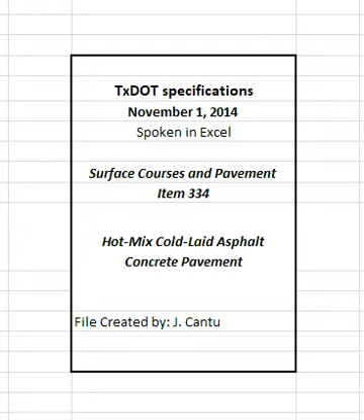2.4.2 Primer. Provide an approved asphalt primer consisting of a blend of asphalt cement and hydrocarbon volatiles. 2.4.3 Water. Provide water that meets the requirements of Item 204, Sprinkling. 2.4.4 Additives. Use the type and rate of additives specified when shown on the plans.